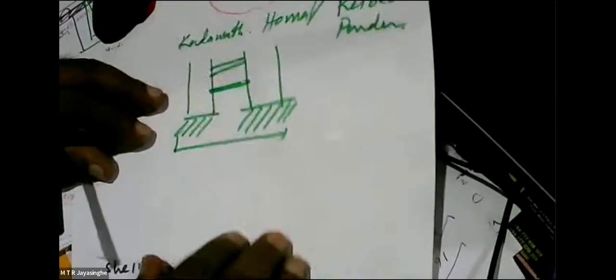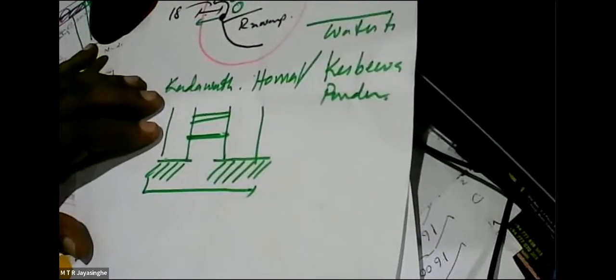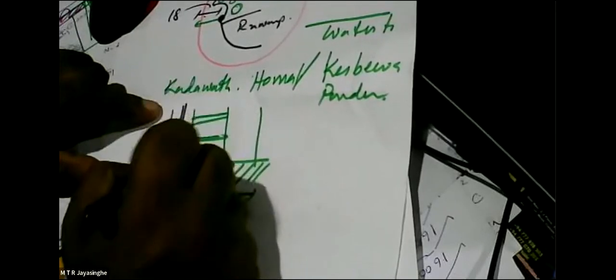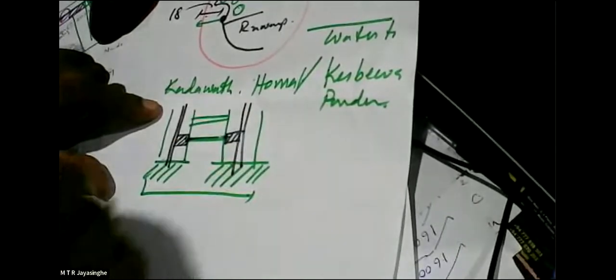So when you have coupled shear walls, you have coupling action, and the whole thing behaves as one unit. And when you do that, I showed you how to do the modeling. But now, if you don't have SAP, how do you do the model? We create a column, we create another column. Then we create a strong arm for each leg. Then we create the real beam, the coupling beam.